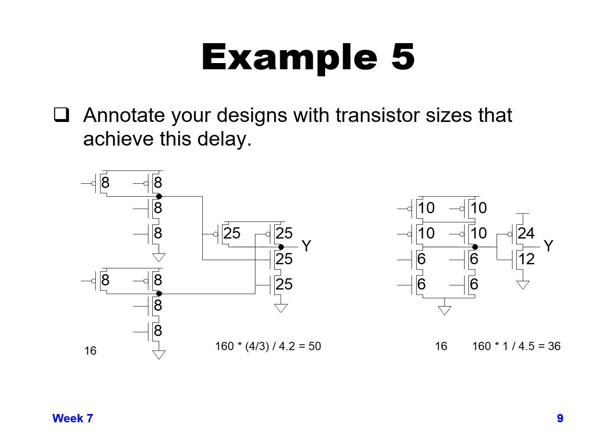So here they're just trying to balance it as close as you can get and stay with even integer multiples. So we get 10 over 6 in order to get the value of 16. That's the only reason that was done. In reality, you might decide that you'd rather do 10 over 5 and actually only have a value of 15 there, but we're doing 10 over 6 so that we get the exact value of 16. For the next stage, we do the same sort of function in order to figure out how big the next stage needs to be.